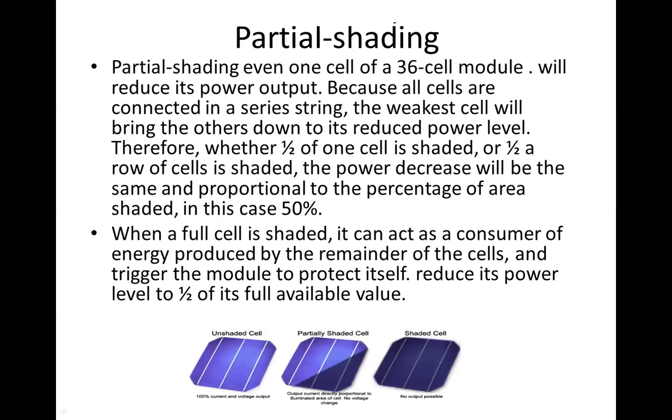Now I need to talk about partial shading. Shading half of a cell is the same as shading half of a row, because these are all connected in series.